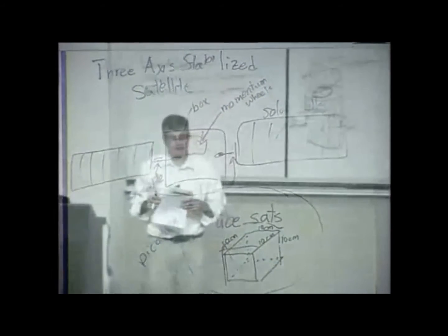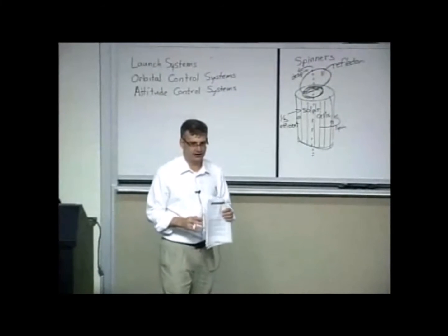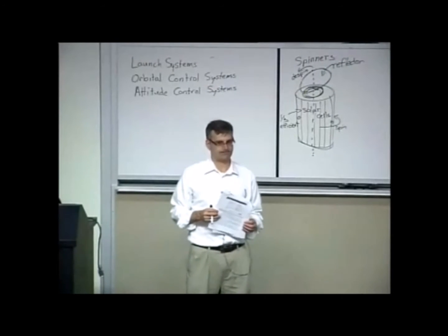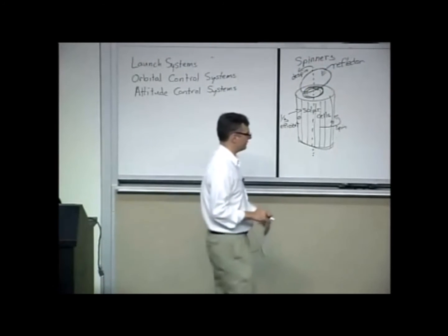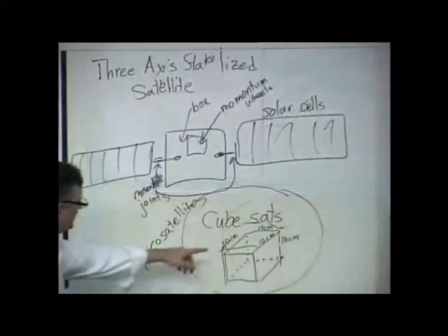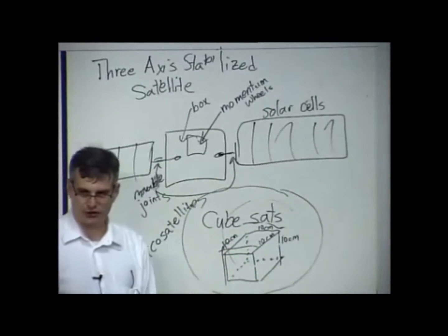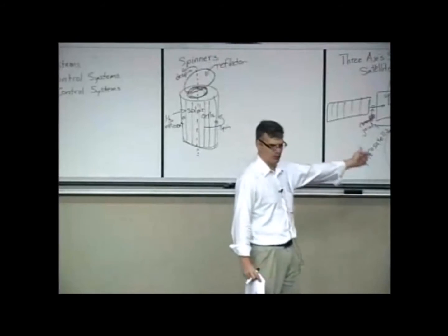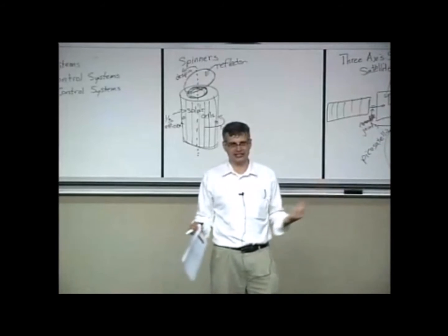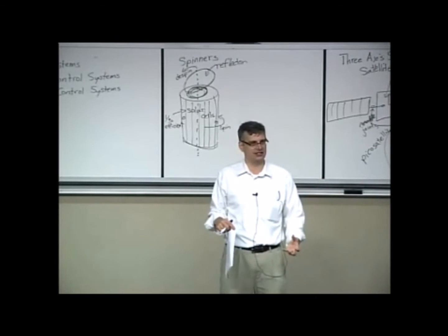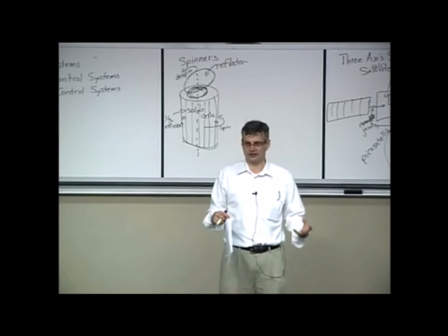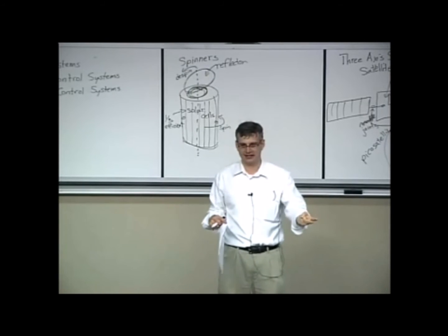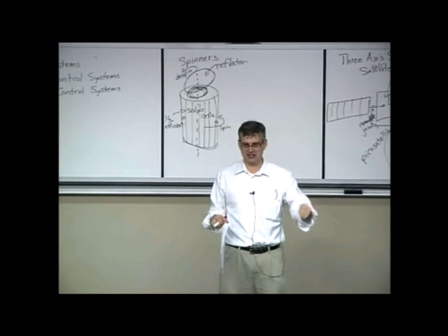Any questions so far? Yeah. Solar cells? Yeah, you usually put at least a few solar cells on every facet of this thing to make sure that you get some sort of pickup, since you don't have any real attitude control. I think some people have tried to put little momentum wheels on here, but usually the space mission is not super sophisticated. You're usually trying to measure one thing with the CubeSat or do one basic task of communications. And so